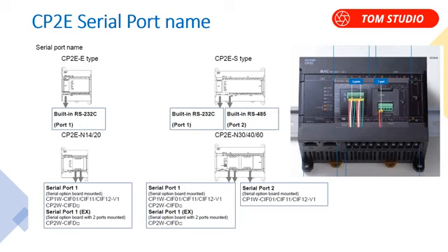You must match up the hardware and software settings. Port 2 is purely for CP1WCIF01, CP1WCIF11, CP1WCIF12. You can't use the CP2W option board on port 2. In this video, we are using an option board on port 2.